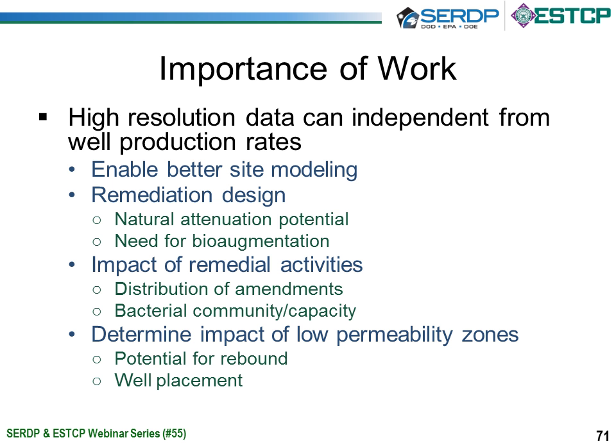For remediation design, it will help better understand whether or not natural attenuation is occurring, and if so, in what formations. It could help look for the need for bioaugmentation, not just in general, but in very specific zones. It can be used to evaluate the impact of remedial activities. So if you bioaugment or you biostimulate with edible oil, did it get to where you needed it to go, and is it still there? Is it having the activity that you want it to have? And then probably most importantly, the impact of the low permeability zones. What's the potential for rebound? Where should you be putting your wells? And what's the fate of the chlorinated solvents trapped in these low permeability zones?